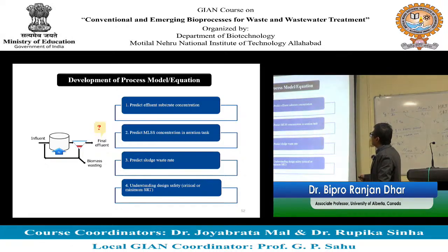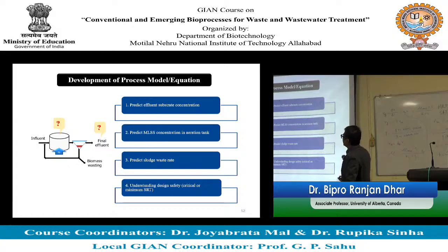So we want to get an equation that can allow us to calculate the final effluent concentration by manipulating the operating parameter like SRT. We want to calculate the MLSS concentration, or biomass concentration, in the reactor, and we also want to estimate biomass wasting rate, which we already have an equation for, and at the same time we want to learn about design safety in biological process.